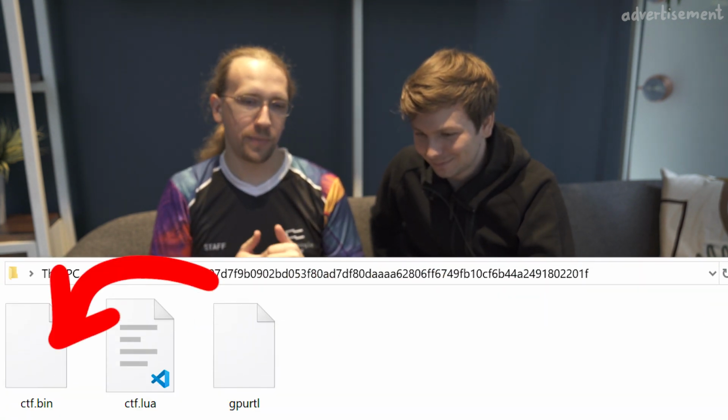So to keep you from guessing, the challenge was basically an FPGA simulator implemented with Rust and the GPU, so in shaders basically. And what you get, the binary file, is the bitstream for this FPGA. The FPGA has over 2000 lookup tables, or logic cells, whatever you want to call them. Each one has 4 inputs, then a lookup table, and 2 outputs: a normal output, and the other is a register, a flip-flop output.